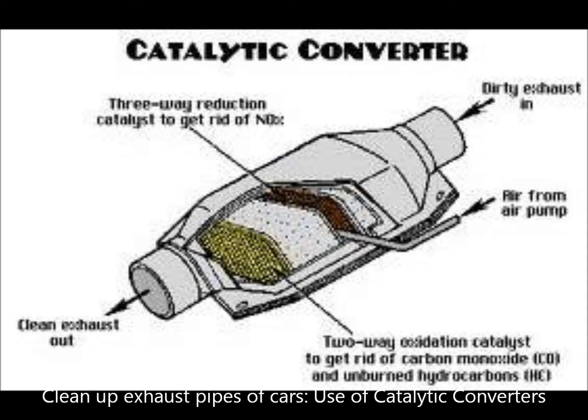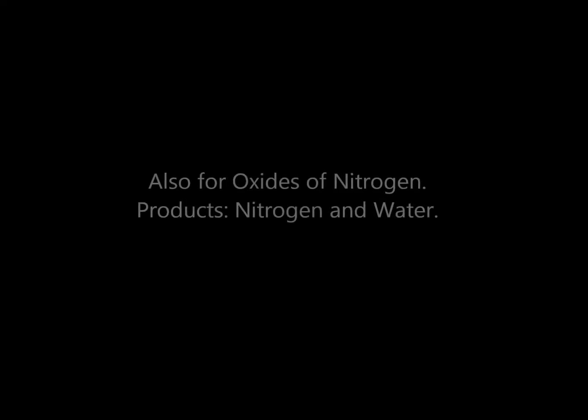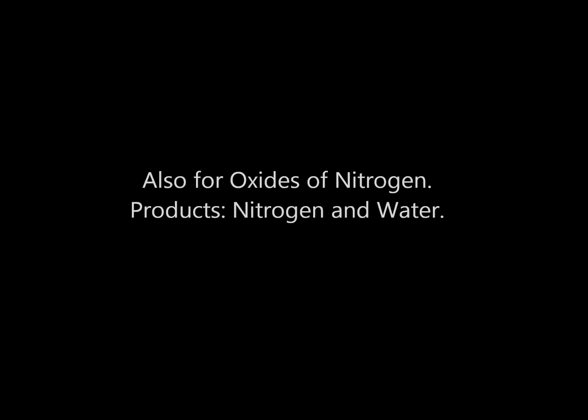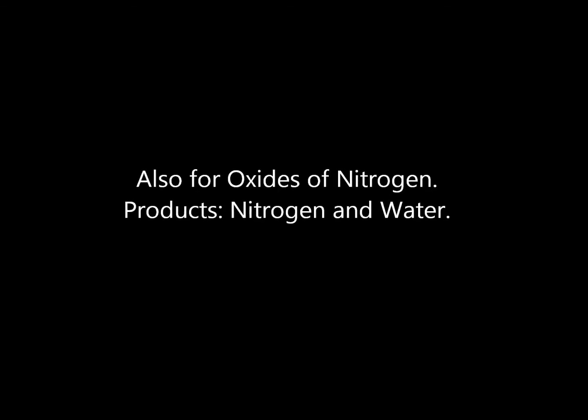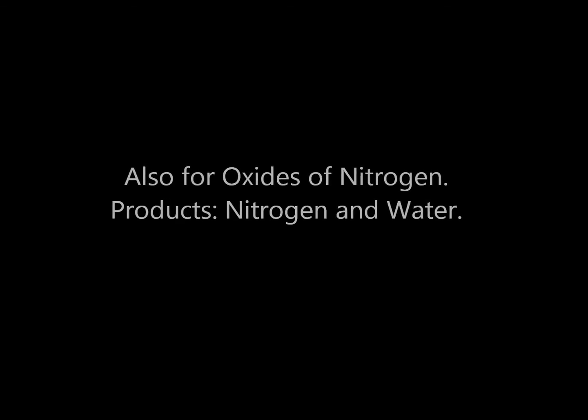Carbon dioxide and water are both harmless in a way. The catalytic converter is installed in the exhaust line between the exhaust manifold and the muffler. This catalytic converter is also used to remove oxides of nitrogen, where the gas produced will be nitrogen and water, instead of carbon dioxide and water.